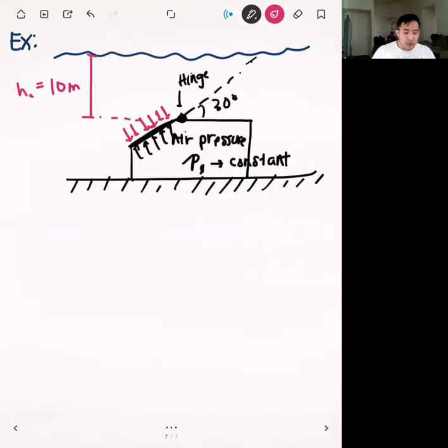And because we have the fluid on the outside, this is also going to exert a force. But this force out here respects the fact that we have a hydrostatic fluid. And so that force, the distributed force, just like we said before, is going to be higher at higher depths. So some other pieces of information. Our gate here is circular. And so the diameter of the gate is 2 meters.